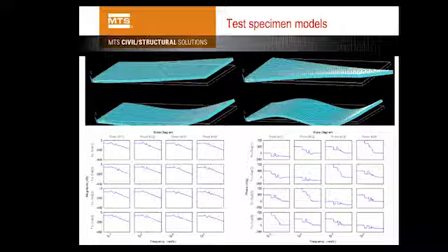But for this case study, for that steel plate we are testing, remember, from the beginning, we first built an FEA model. Then we did a reduced order model out of that FEA model, those two at the lower part. So we convert the FEA model into basically a transfer function matrix model.